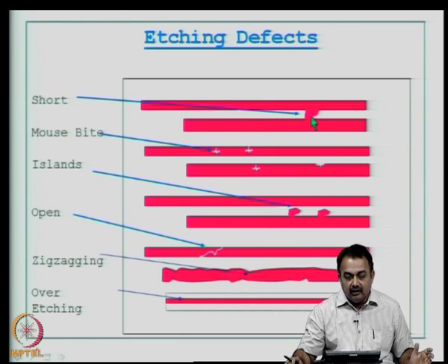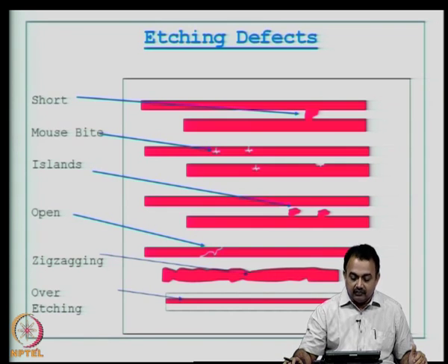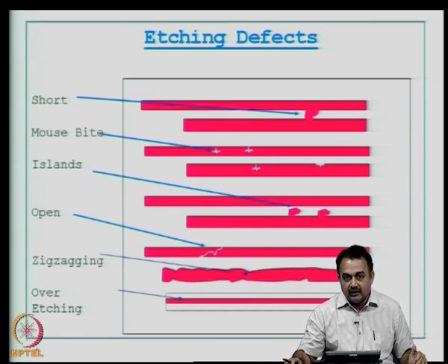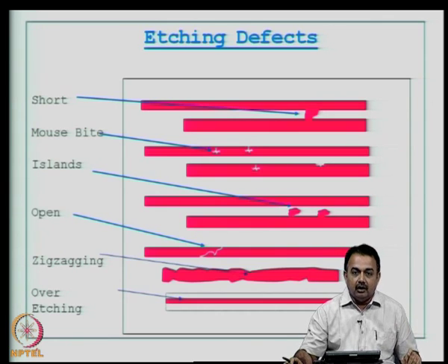One of the reasons could be that a strip of mask or photoresist is present there which you have not noticed. So, there is a problem with the developing process during the photoresist application or image transfer, or it could be that it has not undergone the right exposure in that particular area, or there could have been a bubble which basically has affected the exposure and it has got translated finally into copper.